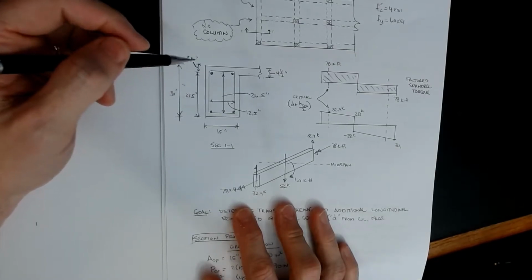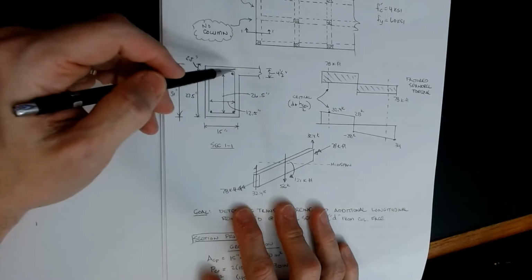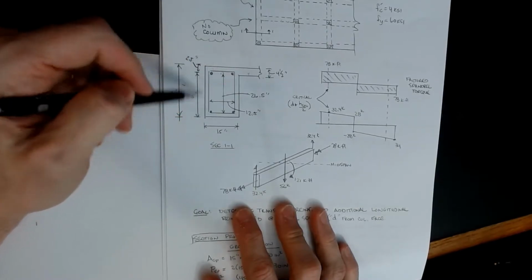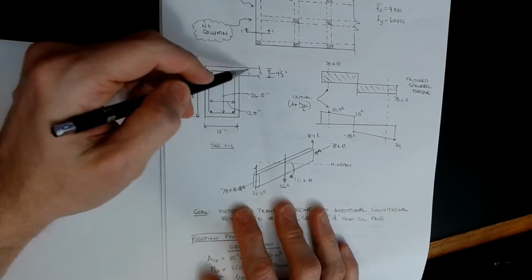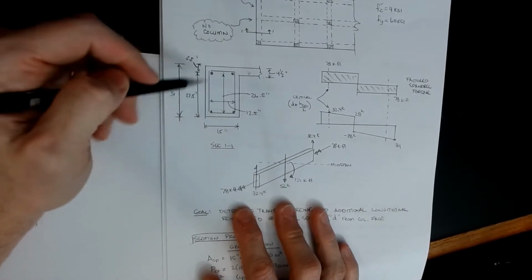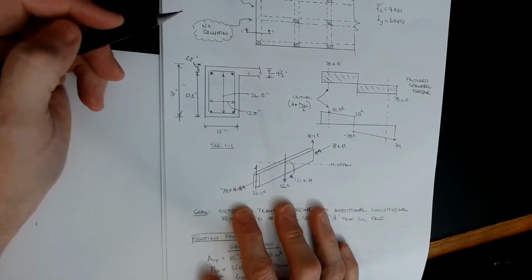Now, one thing that we're going to assume in this is, in mechanics, often when you have torsional shapes and then another guy tying into this guy does provide a little bit of restraint and some resistance. We are going to neglect his contribution to the torsional value of the beam. We're going to make the beam do all of the work. And that should kind of make sense.